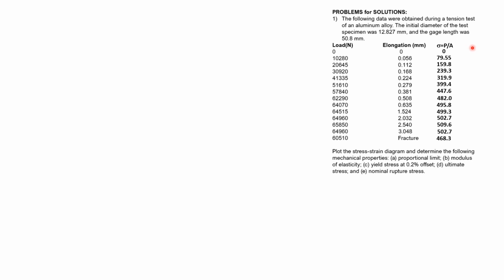Then for the strain, let's solve for the elongation first, from stress times length over E. The modulus of elasticity E here is, of course, 200 gigapascals.